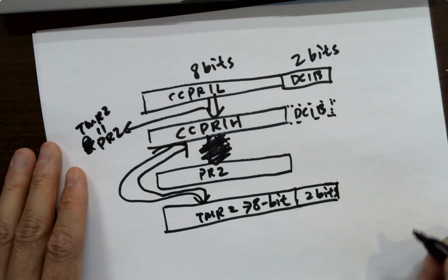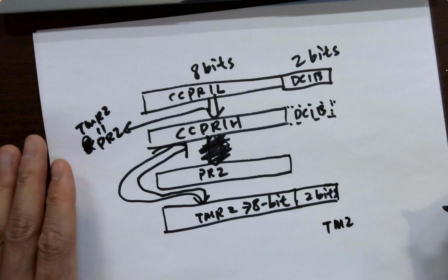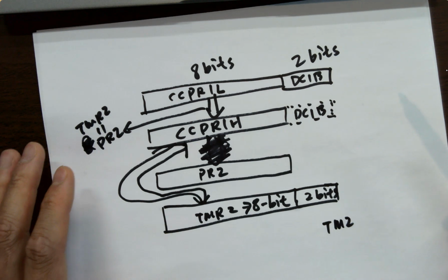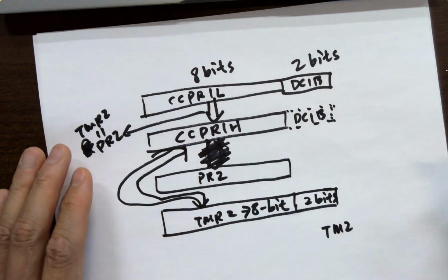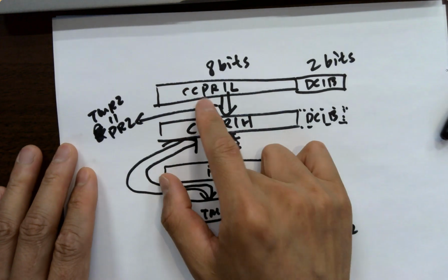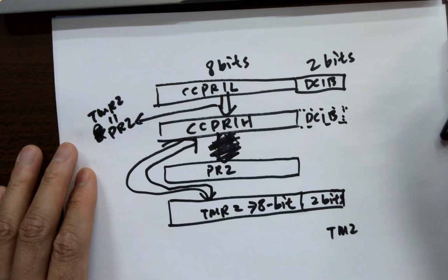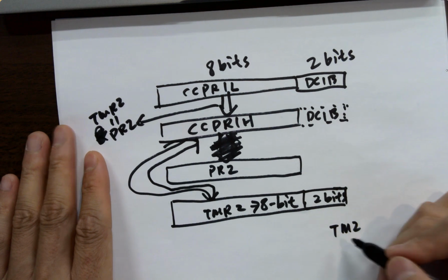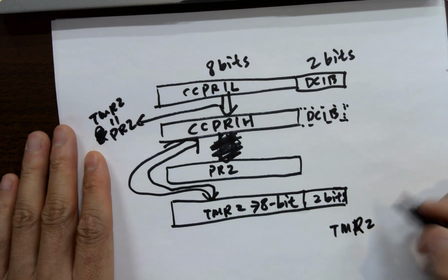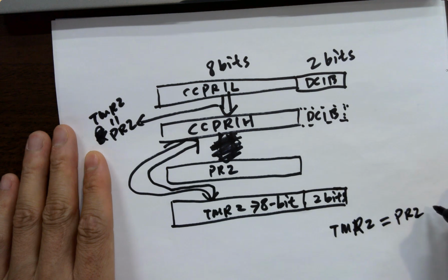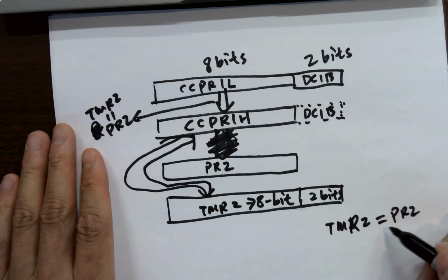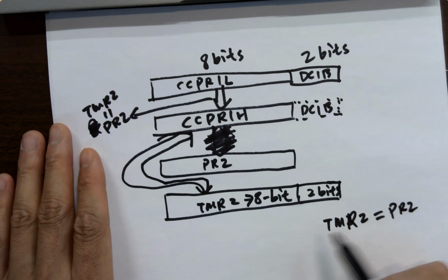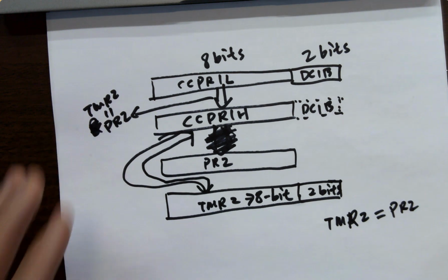So another question here is when timer 2... Oh, that's probably why. I'll talk about that later since I didn't design the hardware here. It's like taking one more cycle here. Is that why PR2 plus 1? I don't know. Who knows? We don't care. So timer 2 equals PR2. It says on the data sheet it equals PR2. It didn't say PR2 plus 1. That's interesting. So let's assume it's because it's not a huge difference. Let's just ignore that for now, okay?